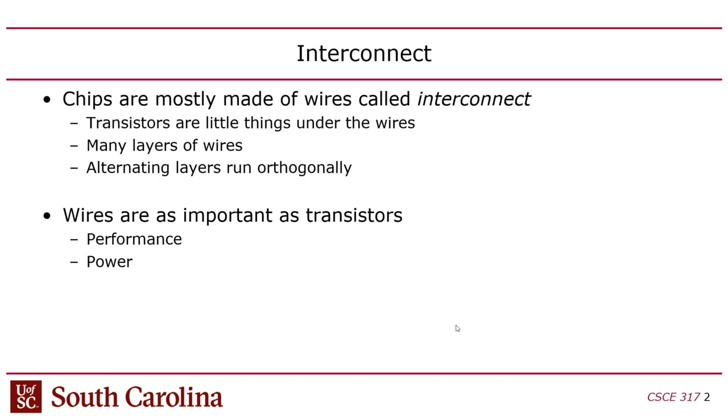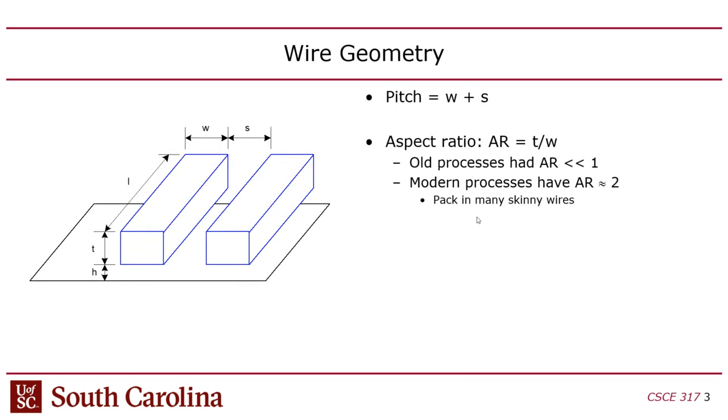but we can add the wire delay to the gate delay. In practice, I think these days the wire delay is usually higher than the gate delay. So it's a major factor. Okay, so what do we need to know about wires? Well, ultimately, we need to know the resistance and the capacitance. It works just like gates.